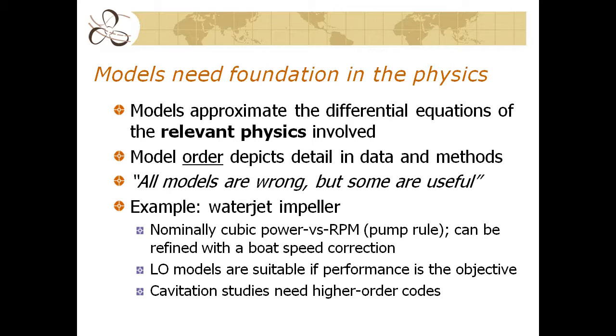Now, if our objective of analysis is to look at things like cavitation or design inflow so it better matches or integrates with the impeller, then of course we need higher order codes. But the nature of the problem, we have to find the problem, understand the problem to fit the order of the solution to that.